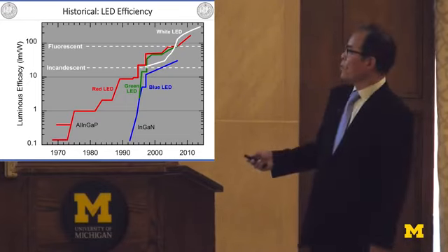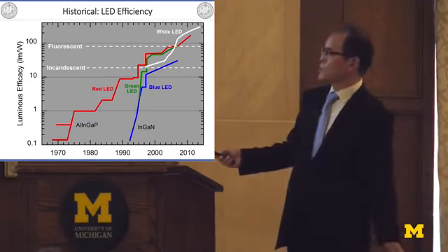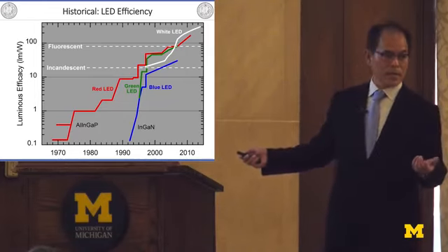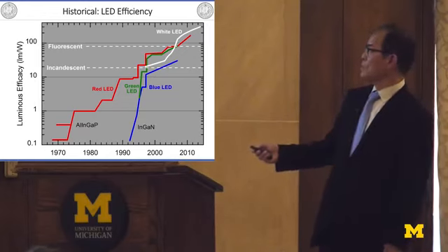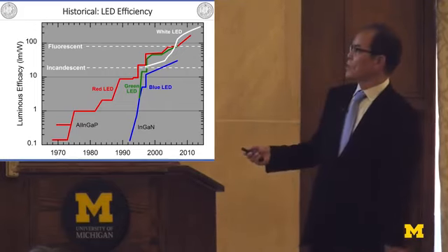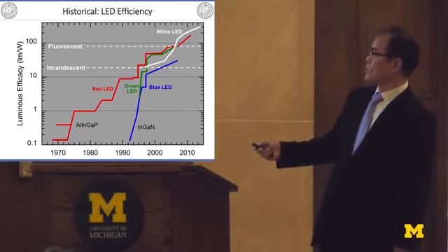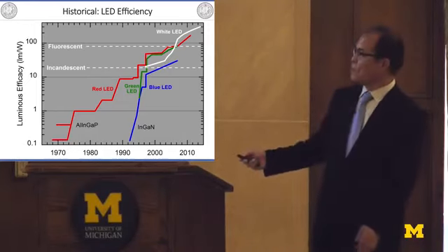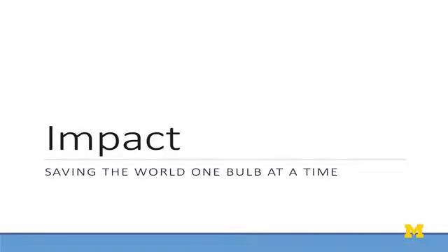It took only 4 years because I changed the material. For red LEDs I used aluminum gallium arsenide. I changed the material from aluminum gallium arsenide to nitride, and I also changed the crystal growth technique, from liquid phase epitaxial growth to MOCVD. So I changed two things. Everything else was the same process. That's the reason I needed only 4 years to develop blue LEDs.